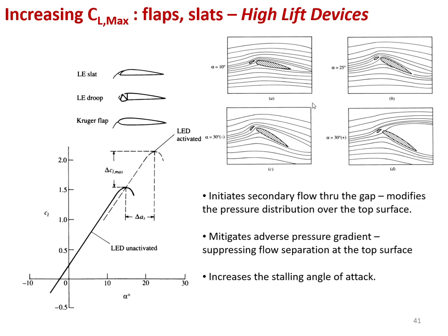The stall happens because of flow separation. If you create a mechanism that attaches the flow and forces more attachment, you are going to see a later stall. And this is also obvious in the graph. So with the leading edge flap activated, you can see the stall condition is delayed, which effectively means your maximum CL is also going to increase.